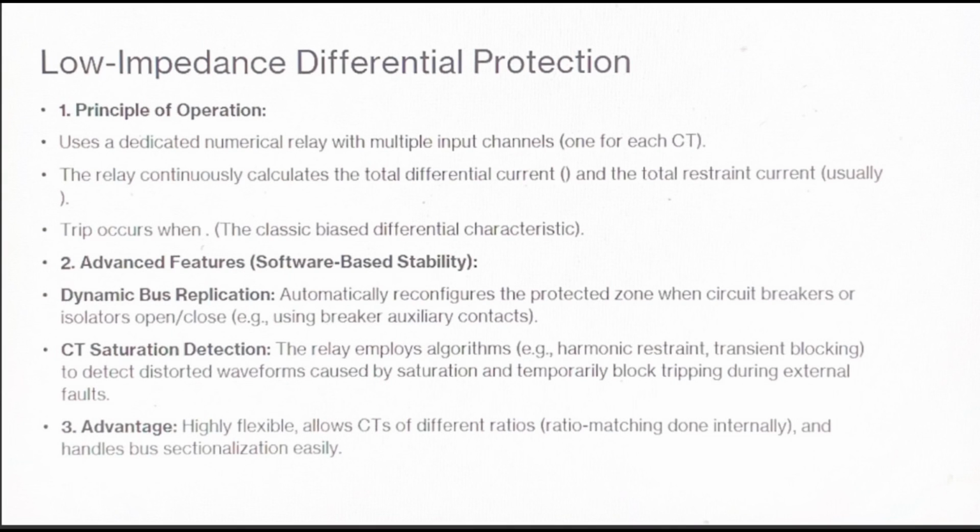The principle of operation is based on bias differential protection. The numerical relay calculates two values, the differential current and the restraint current. A trip only occurs if the differential current is greater than a threshold that is proportional to the bias current. The real power lies in the advanced features.